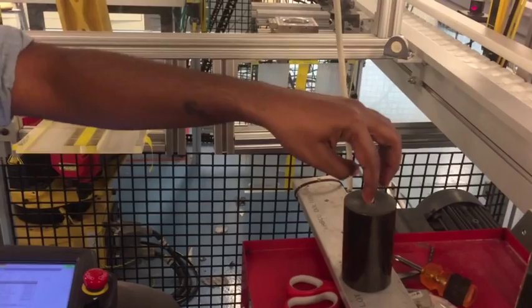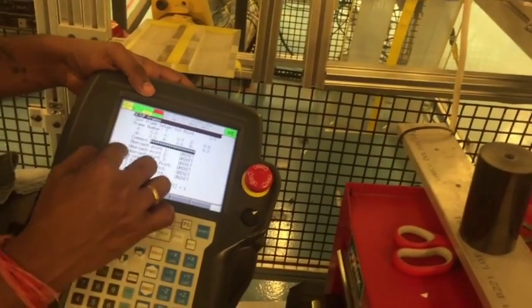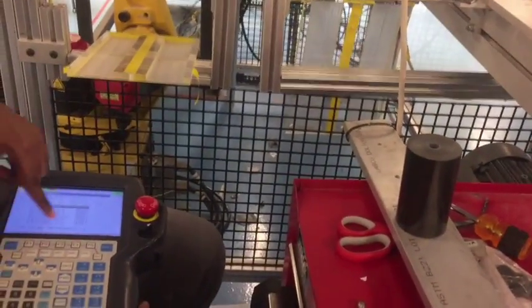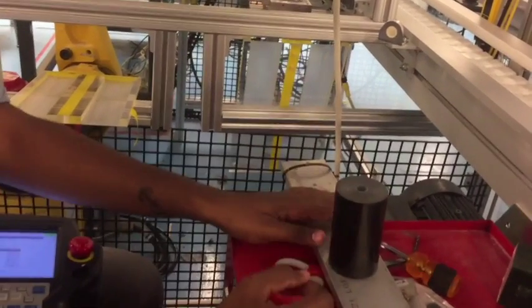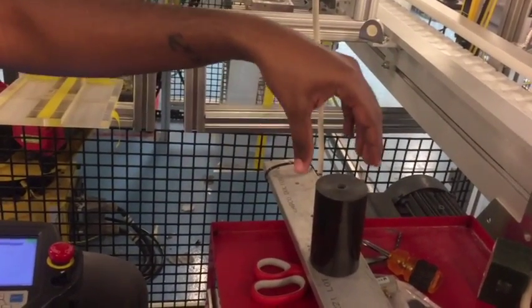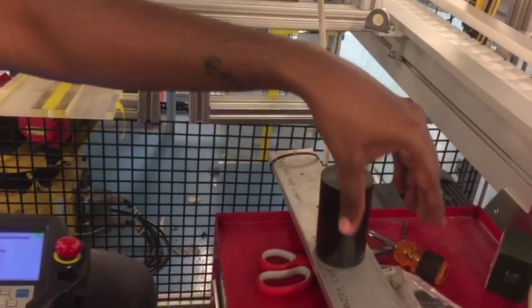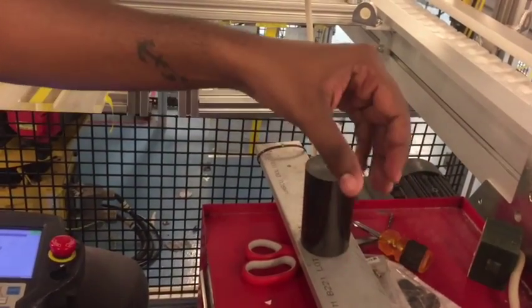Then you take your gripper and align it with the horizon of this thing. That is regarded as the orient horizon point. Once these 4 points are recorded, you go for the x direction point. You can define any frame you want. If you want your x like this, y like this, and z, in a right-handed coordinate system, you take the robot gripper and move it linearly along this direction for a particular distance, and it records that x direction point. You go through this, press record, and it records for you.